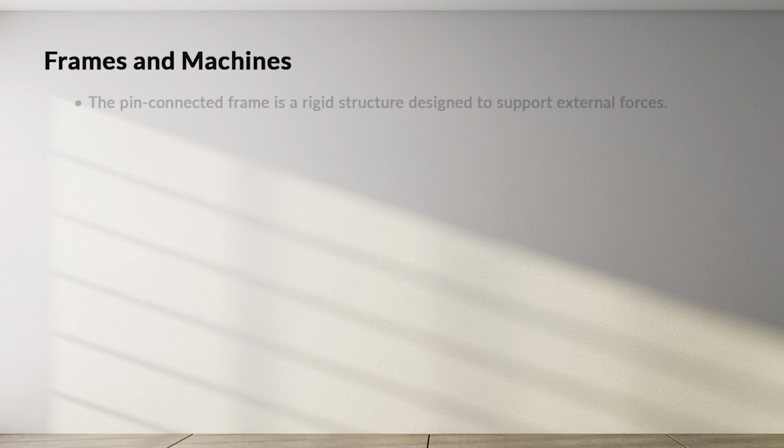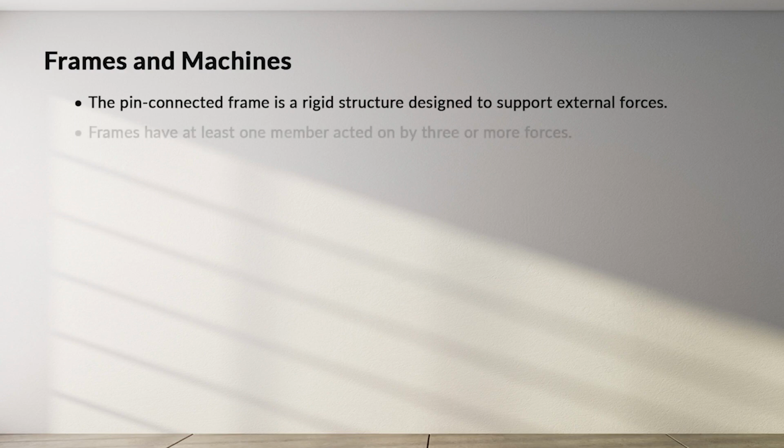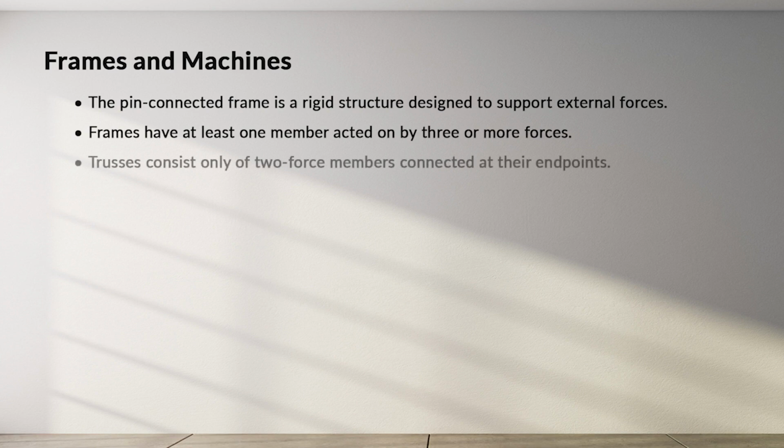Like a truss, the pin-connected frame is a rigid structure designed to support external forces. Frames have at least one member that is acted on by 3 or more forces. Trusses consist of only 2 force members connected at their endpoints.